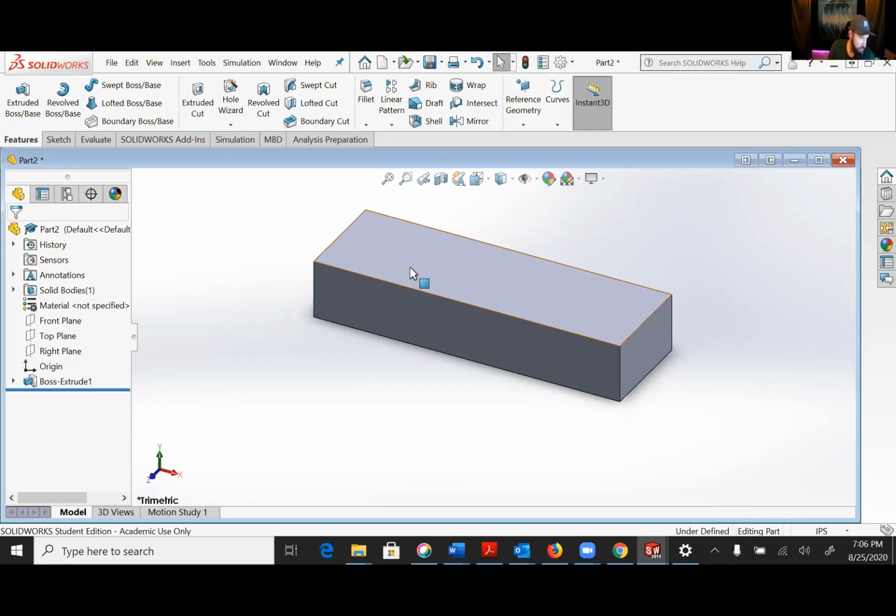Did you guys know that you can hold the right mouse button and swipe the mouse in the orientation you want the object to go? Is that only in SolidWorks? Is that universal? Just SolidWorks that I know of, but I accidentally found that because I was like, how do I actually orientate this thing?